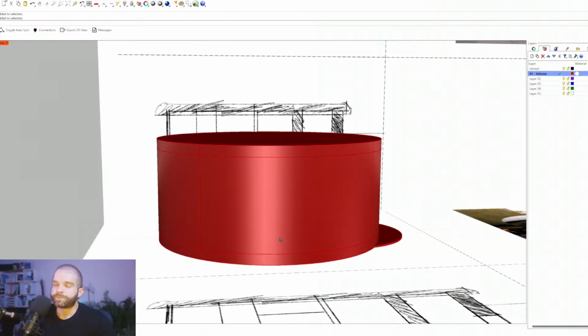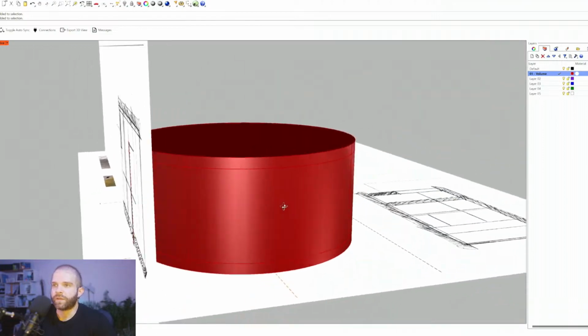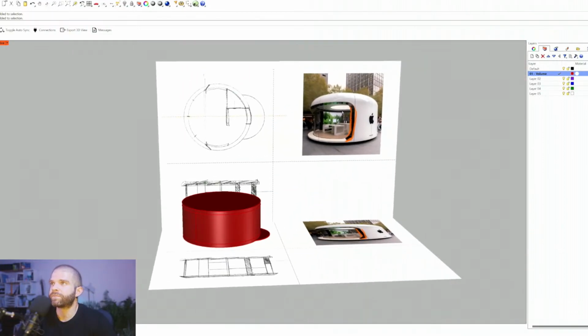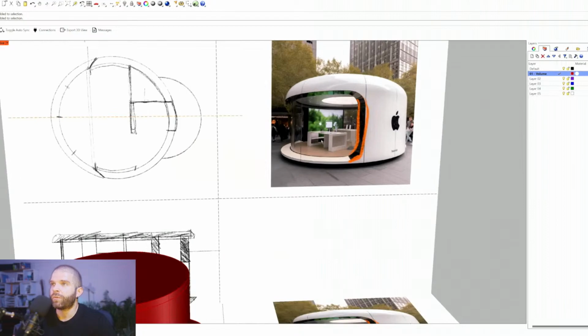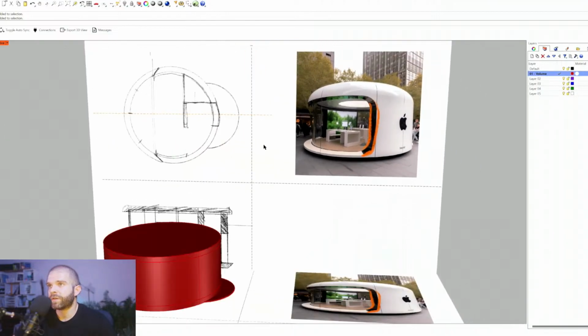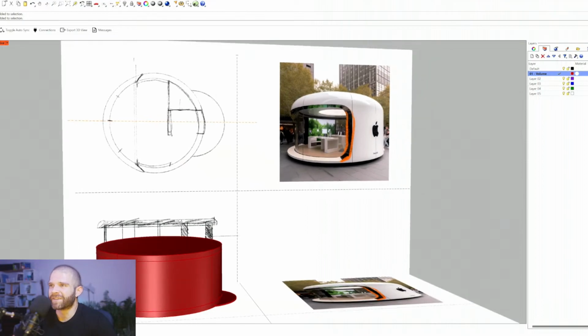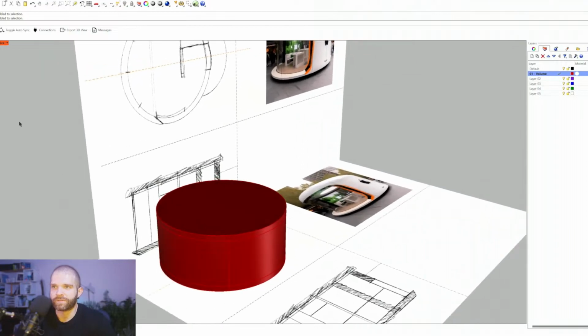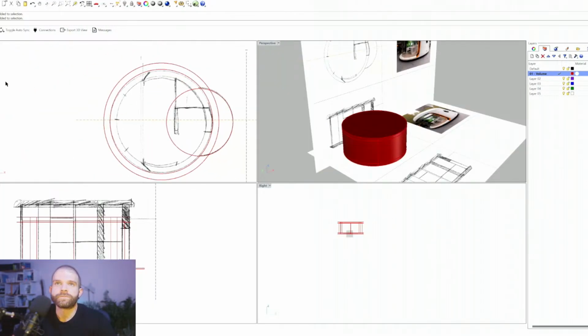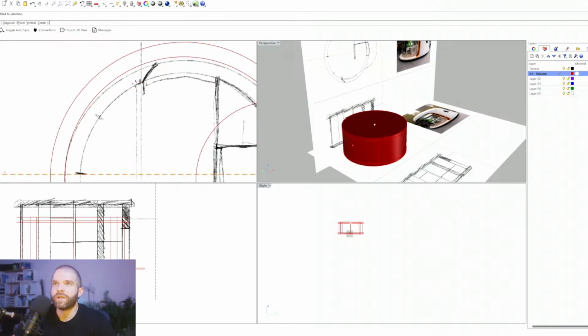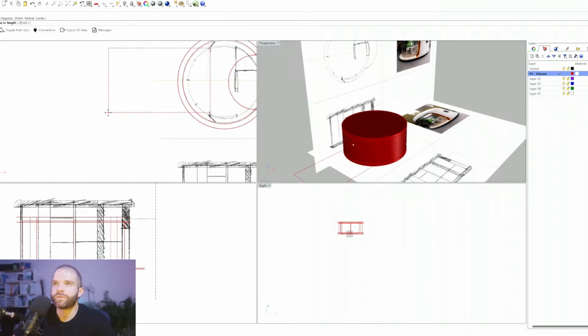So how do we start making all this become this structure? Well, we're going to start using booleans to basically create this shape right here and then mess with the edge conditions a little bit. Really, what that is, I tried orbiting so I could see the side of the AI image. We're just going to cut a rectangle right through this thing. So we're going to go to top view and do a box. Actually, the command is box. We'll line that up to the inside wall a little bit. Be kind of loose with it.